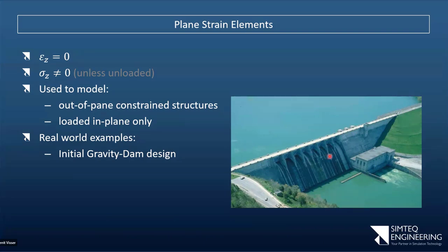So in this case, we say the strain in that direction is 0, and we do a cutting plane somewhere over there. We already see a couple of interesting complications to the assumption. One of them, that angle is not quite vertical, so we already have some slightly strange strain in that direction due to the stiffness at that location. In addition, we've got these buttresses or stiffeners, depending on the industry you're in, that we cannot model with this because the assumption is it's one section and that section stays constant. Yes, we can neglect those, but for a first order answer, I can get a reasonable answer.